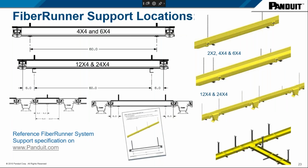And here's where I wanted to get into some of the FiberRunner support locations. As you're considering how often you should support your FiberRunner, we recommend that our customers support every 5 feet. So these are best practices to follow. And when you have a joiner, such as what we're calling our coupler, what we're showcasing here, you should have a bracket within 6 inches.